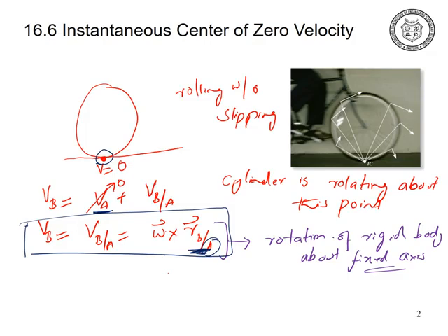So in the present case, as the velocity of the contact point is 0, when we have to find the velocity of any other point on this rigid body, the position vector has to pass through this contact point. Let us say that this is the particle B. What will be the velocity of this particle B? The velocity will be tangent to this circle, or tangent to the path. So what is RB with respect to this contact point? This is RB with respect to the contact point, and it acts in this direction.